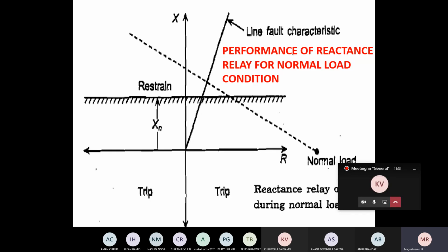Finally, during a power swing, in case of outage of one line out of two parallel lines transferring power from source to load, there will be a swing in the delta in order to move from the initial value to the new equilibrium value. While doing so, the impedance seen by the relay changes as delta swings.